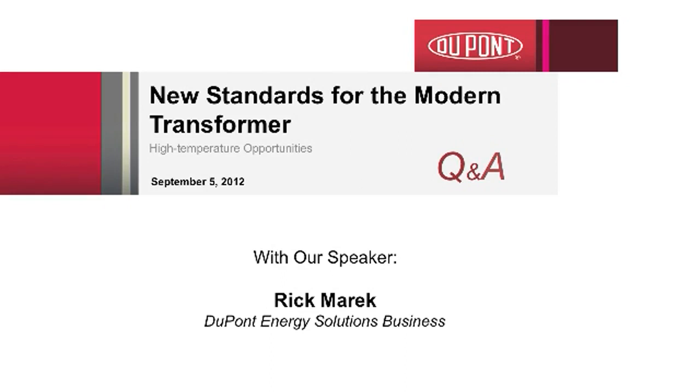the standard for determining the temperature class of these systems has changed, C57.100. So we do not have a number yet for Nomex. After a good deal over a year of testing, we still have not even reached 50% of its tensile strength yet. So it will be a while before we have a final number on Nomex.